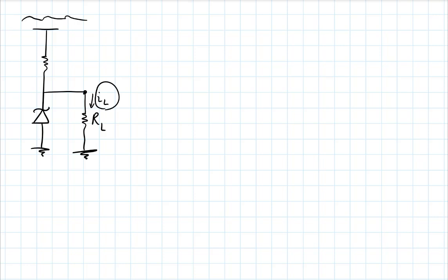Either its current would become too low, it would go below the knee current, and its voltage wouldn't be able to stay around the Zener voltage anymore, so you would lose the regulation functionality. Or you would end up with a current in it that's too high, the Zener diode would be damaged, too much power dissipation in it, right? So yes, it could do this, but for a range,